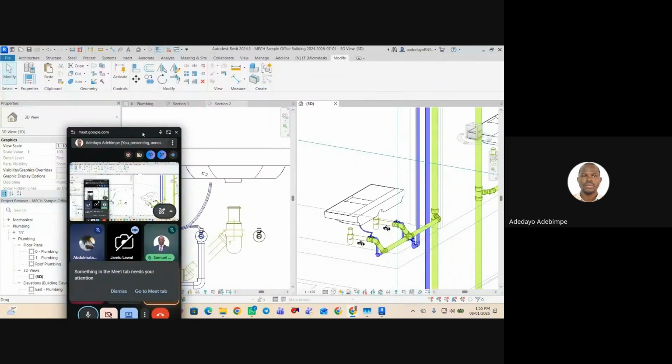We'll say, okay, we are using a gravity supply system, or a boosted cold water system, maybe boosted from the roof or from a break tank, or connecting to municipal supply. From there I'll decide what type of system and what components I'm going to use. Then I'll move on to my calculations. But as I said, this class is a modeling class. We'll eventually get into building services proper, the design and calculation aspects.